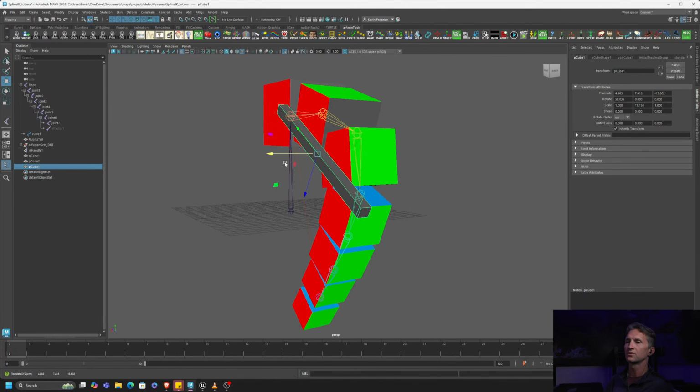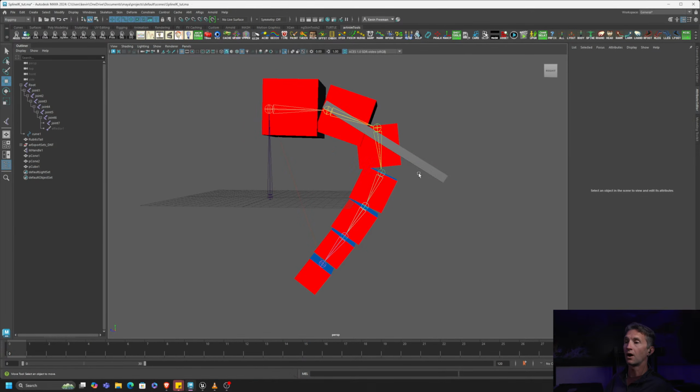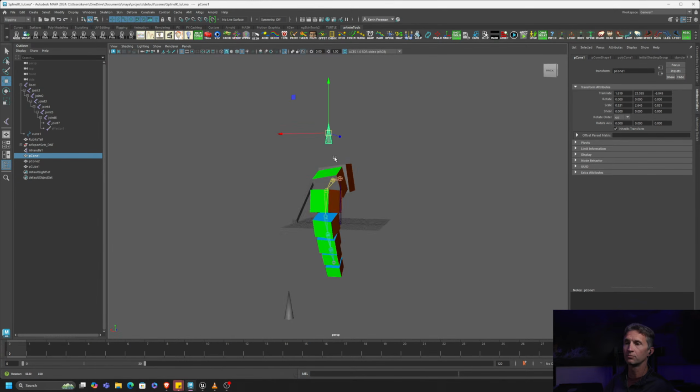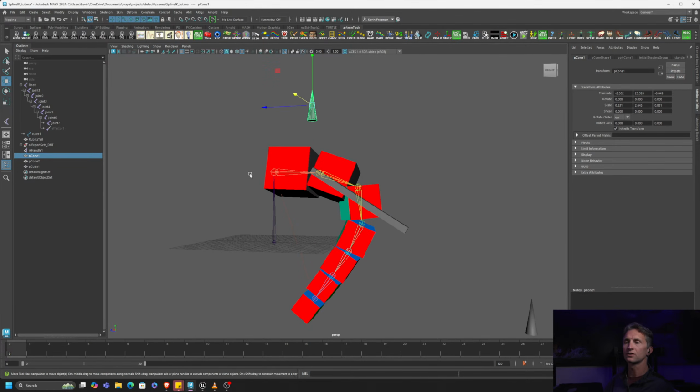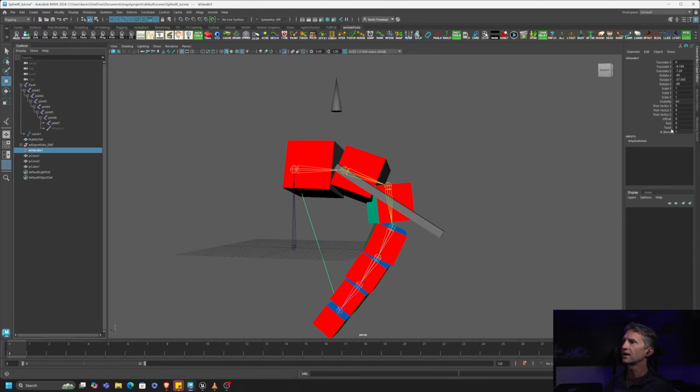So anyways, what happens here is we're trying to stabilize this, and as a result of it, we're playing a game. Now, what will happen is oftentimes in a rig, when we create the controls, these cones would be parented almost like pole vectors. And by the way, if I move them to the side, you can see they have an effect on which way the twist is going. And then usually you can also affect the twist on top of it. If I click on this curve, if I come down here to IK, here we go. So there's a twist, so I can twist on top.